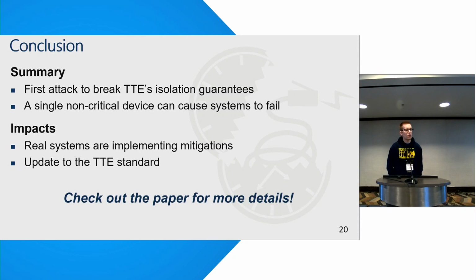Yeah, I would say you don't have to be that lucky. Like I said, we can generally get successful injections on the order of every 10 to 15 seconds. The way it would work is, for example, you would send your malicious frame with the packet-in-packet attack, you turn on your EMI circuit, and generally right when you turn it on, it causes a link reset. So the link of these other switch ports will go down, and as long as your message is somewhere in the queue, when it wakes back up, you can cut it in half.